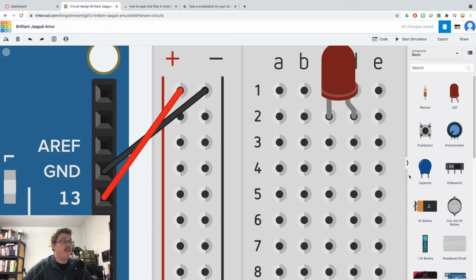So a couple identifiers, you'll notice that these legs are different lengths. The one on the right has the little squiggly bend, which means that we theoretically think must be a little bit longer. Longer anode, positive. One more time. The longer leg is called the anode, which needs positive current. The cathode, smaller, negative.